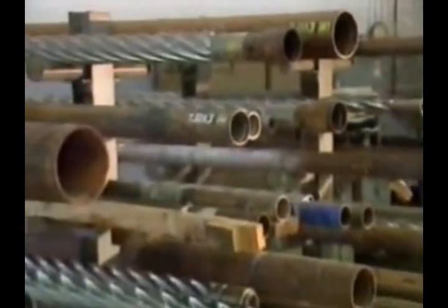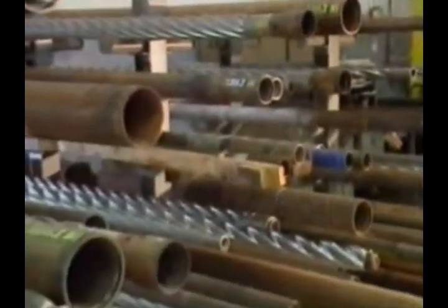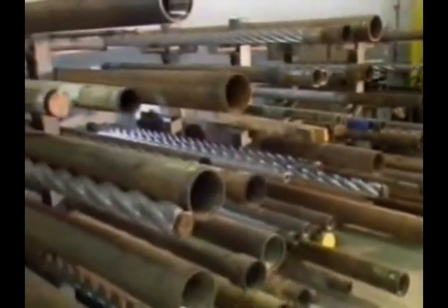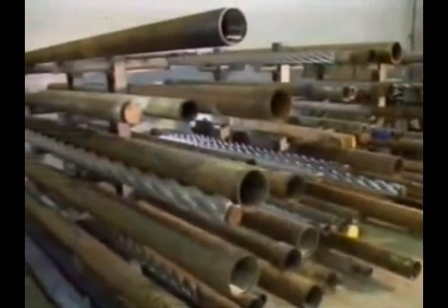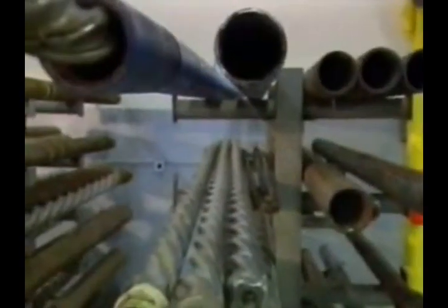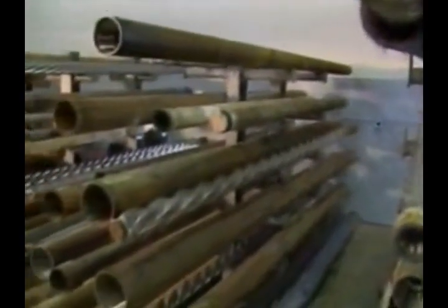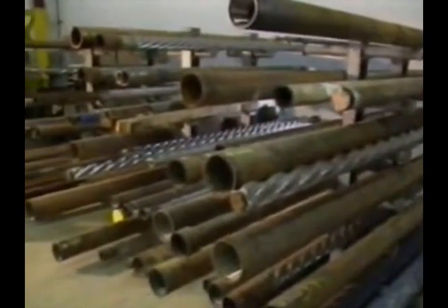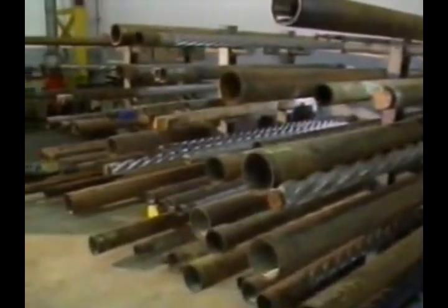This can result in higher penetration rates compared to drilling with a rotating Kelly and reduced drill pipe and casing wear, an important consideration, especially when drilling high-angle holes. Positive displacement motors are available in a wide variety of sizes, rotating speeds, and output characteristics for a broad range of downhole conditions. For more detailed information, refer to the references listed in your manual.